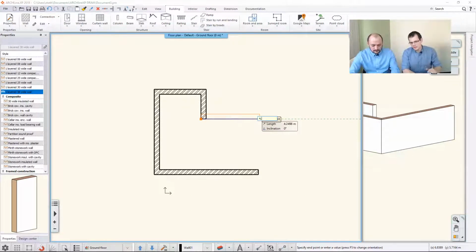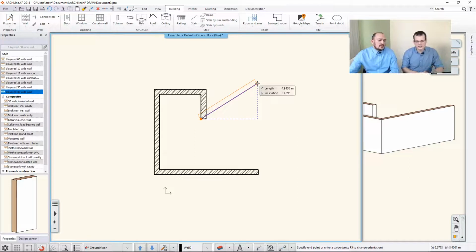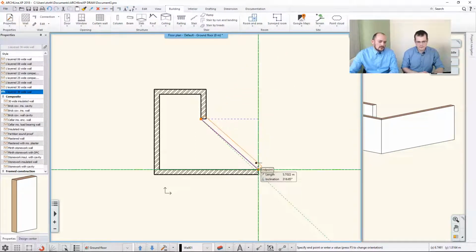At this point, what you could also do, in addition to submitting the number, is snap to that wall which is on south from here. So if you hover your mouse and keep it over the existing corner and you stay over there, see these green lines appear automatically. That's what you wanted to say, right? Yes, that's right. And then you can snap to that point.